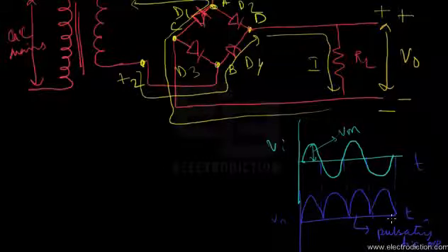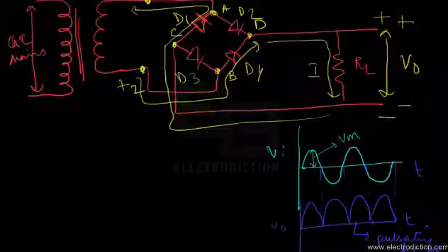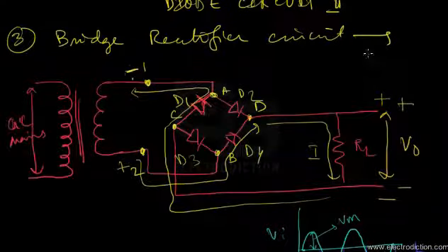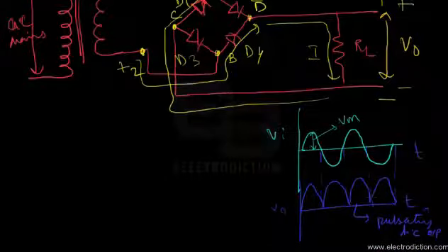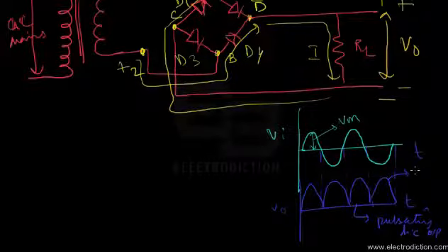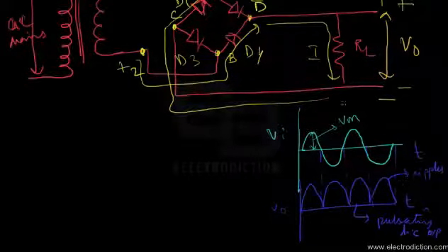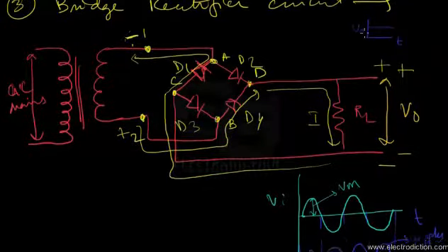Okay, so for a rectifier that converts AC into DC, we need an output that would be a straight line without varying with time. Now this output, as we can see here, varies with time in a far greater way. So the components that we have here that keep on varying with time, all these humps that you can see here, these time variant components are referred to as ripples on the output voltage. So now we just need to smoothen out the ripples so that we can get an output voltage that looks pretty much like a straight line, as in case of a proper DC.